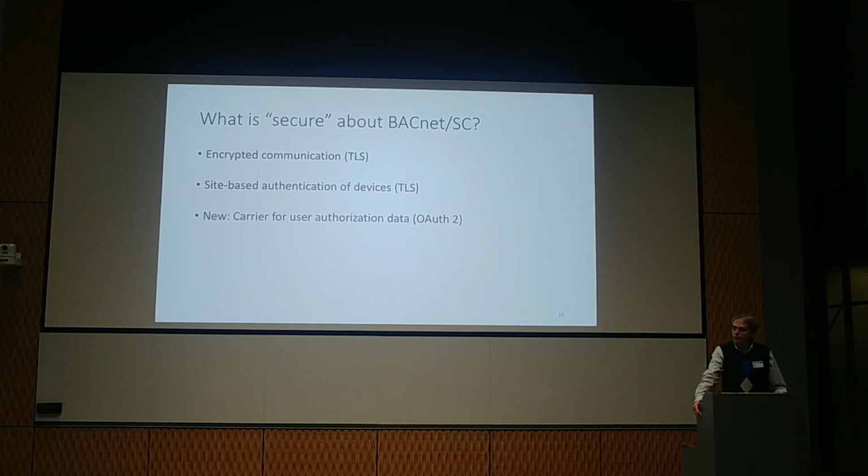We've thought about how to implement certificate revocation too. I'm not going to go into much detail, but if you have questions about it, I'll try to answer them. But the idea there is if somebody steals a BACnet SC device off the wall, you want to be able to kick out that device from your network and also kick out its certificate, so that if someone manages to yank the certificate out of that device and put it in another device, you want to make sure that that new device won't be able to join the network, assuming that you detected that the device was stolen.